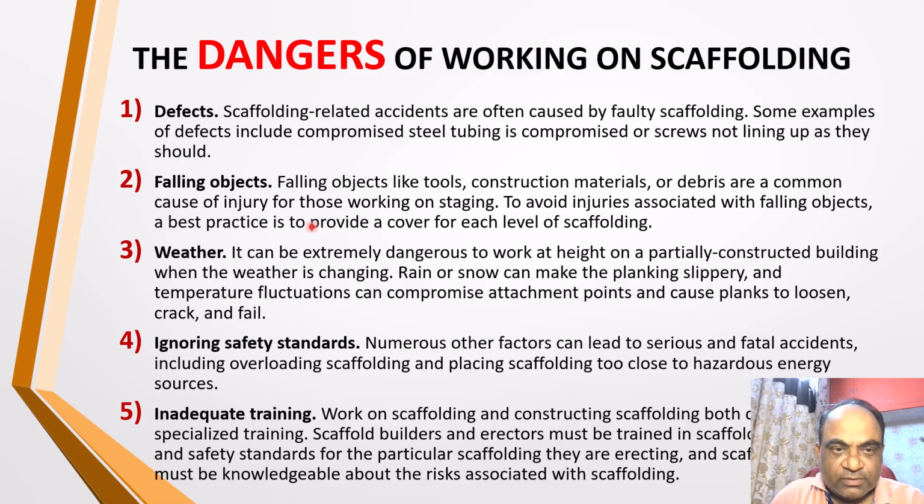People work at different levels of the scaffolding, and material falling from a higher position to a lower position can cause injury to the people working below. So proper cover has to be provided so that even if the material falls, it is stopped by the cover.